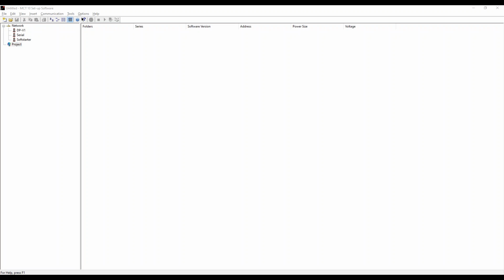Correct. But to choose that, it looks like you have a bit to choose coasting or not coasting, whereas in the drive terminal block, you don't have that. So logically, I almost thought it would say coast inverse instead of coasting for the bit to match the manual. Well, in a way, it is a coast inverse because I'm turning the bit off to coast. Correct, in the same way as the digital input. The bit is inverse. It commands coast when the digital input is off. So it is the same. If I leave that bit off and I just use bit 6 to start, the drive will be coasting. Right.